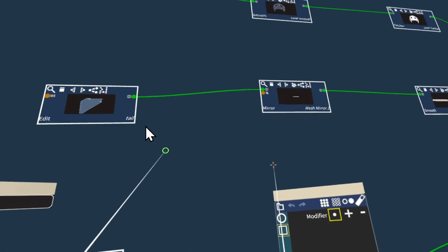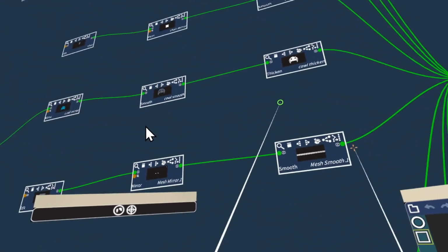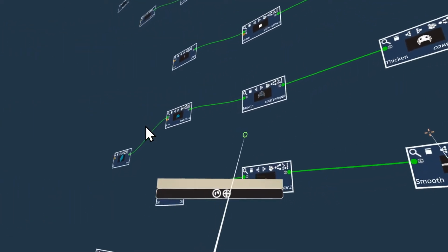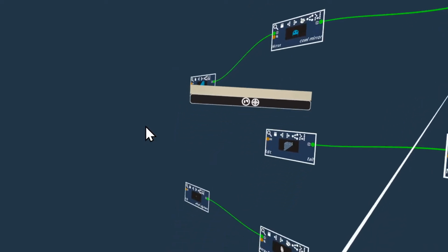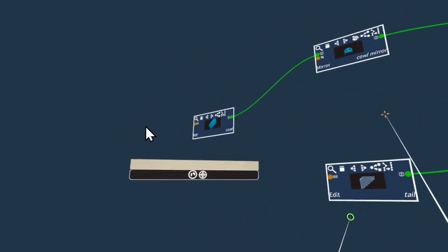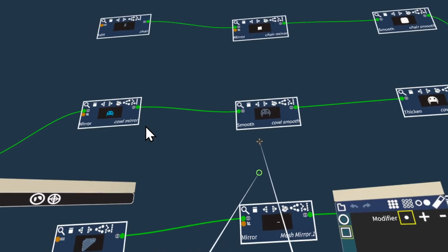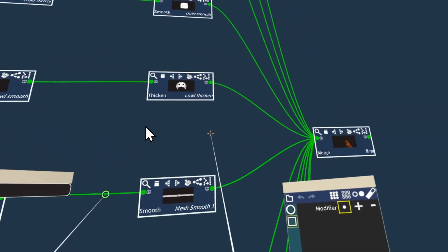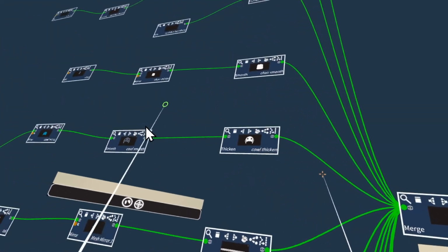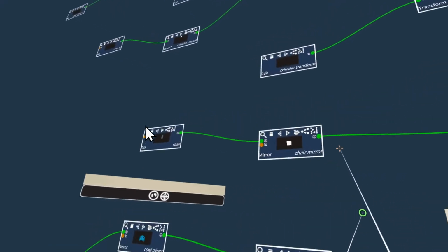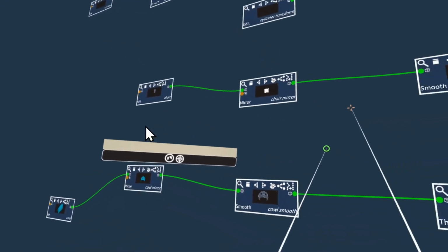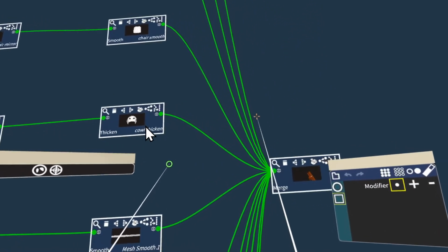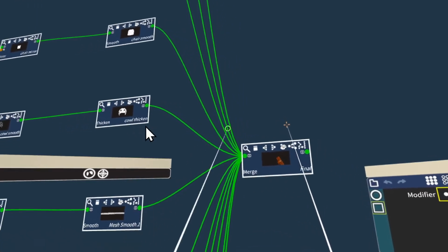It probably looks quite complicated, but don't worry about all the details for the moment. The way it works is you create basic meshes for all the parts of your object, then modify them using functions. These functions are represented by nodes. Examples of functions you might use are mirror, to reflect in an axis, array, to repeat a mesh, and smooth, to round off a mesh's edges. When you combine these meshes using a combine node, you get your final mesh here.